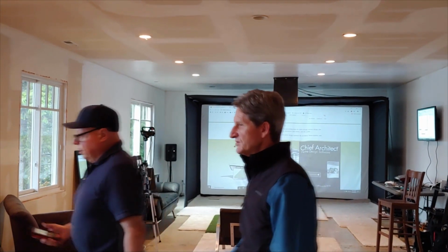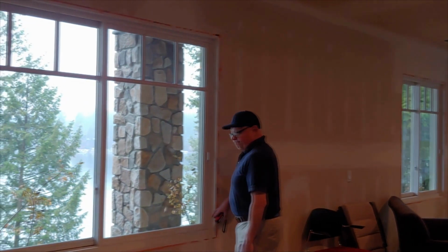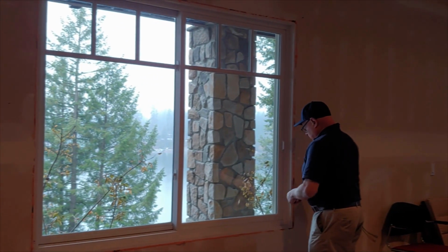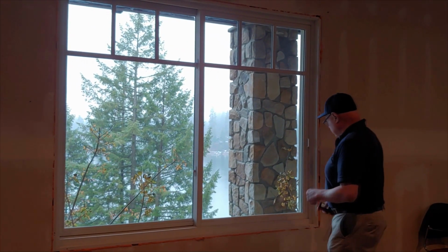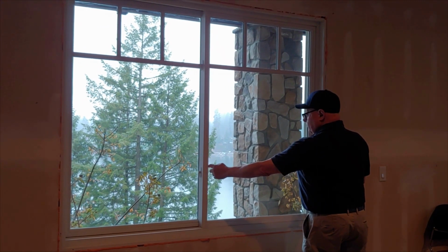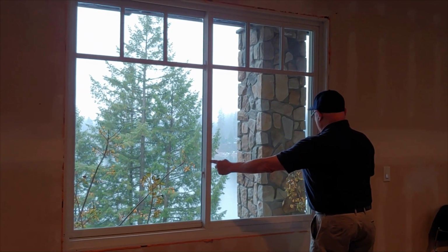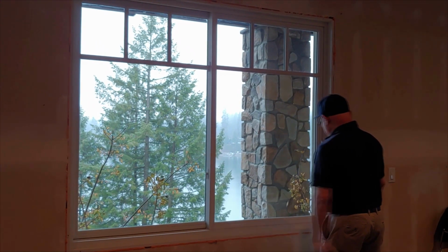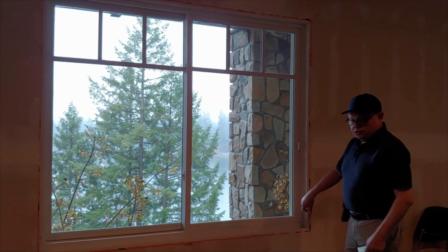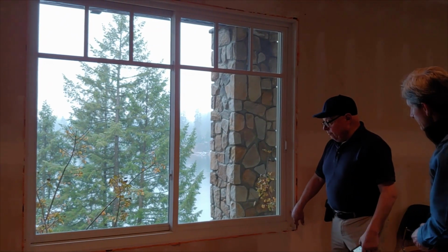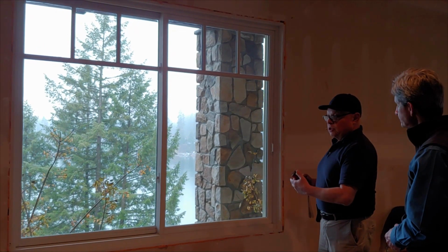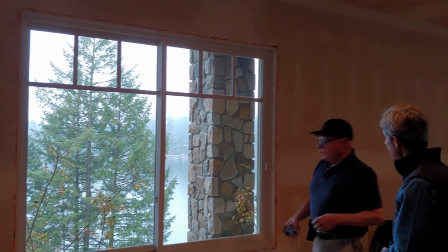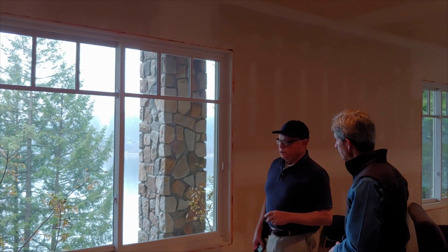Let's take a look at how you're going to measure this window. On a measurement like this, I'm probably going to use the frame right here. It's a sliding glass window. There are a number of different ways you can measure the window. Some people measure the glass. Some people measure the actual window itself, the operable part. I find that the most consistent way is that I measure from frame. Because if the window is a different size or different type, it goes from double hung to slider, there can be some discrepancies there. The frame is the frame, and that's what we use.